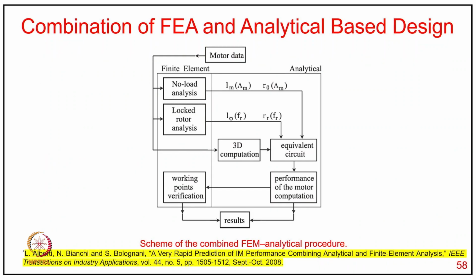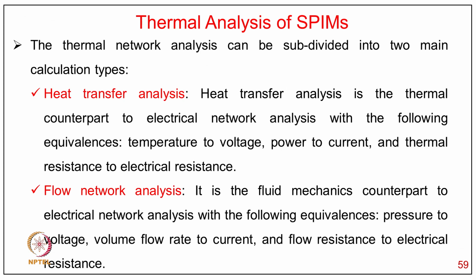This is typically a scheme of the combined finite element analytical procedure, which starts from motor data. Then we go to finite element analysis for typical calculation of no load, locked rotor and working verification. Then analytically we calculate the equivalent circuit, then the performance computation with the equivalent circuit from the 3D calculation, and then verification of the results.